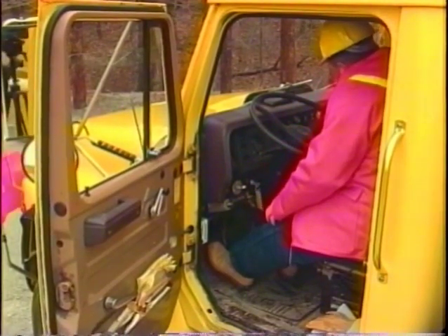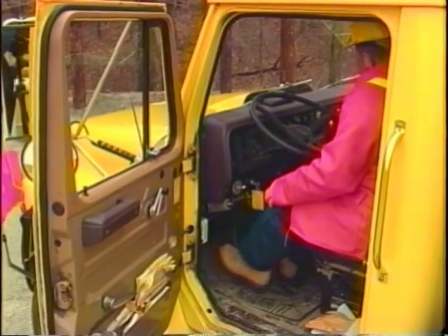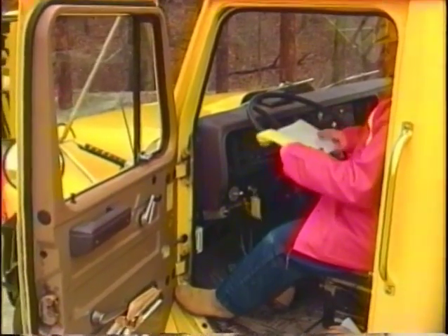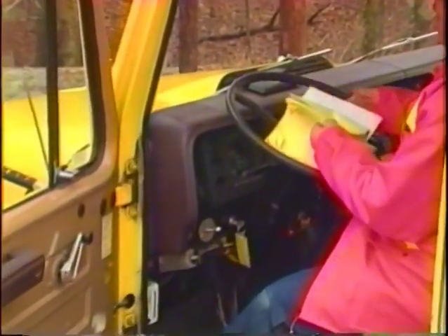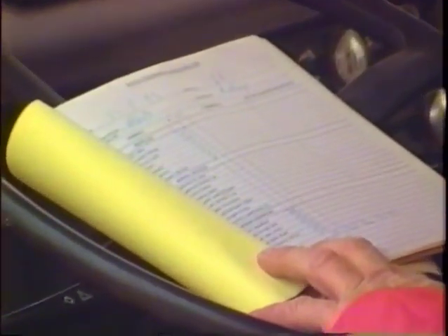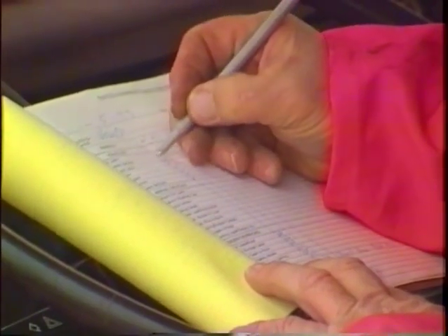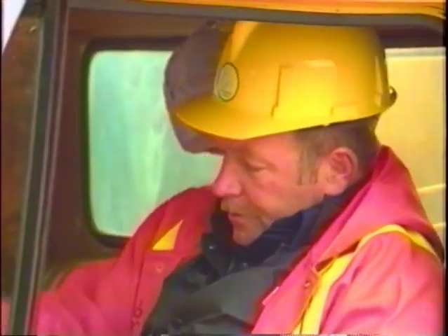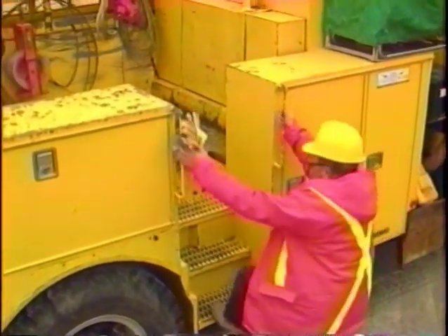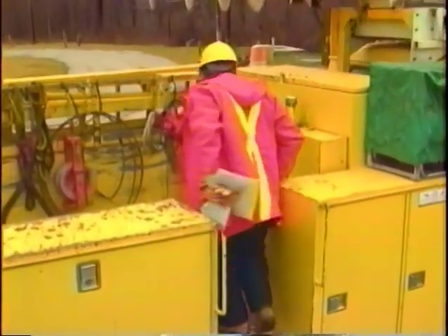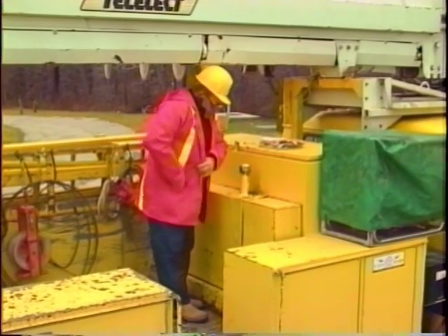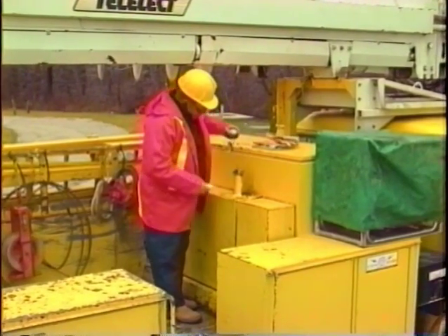It may seem surprising, but in the first part of your hydraulic check, you don't look at the vehicle. Instead, examine the vehicle's logbooks. Are the filters, strainers, or magnetic plug due for servicing? Does the oil need to be changed? If so, arrange to have the work done by a qualified mechanic. The next stage of your hydraulic inspection takes place at the reservoir. Start by checking the level of fluid in the reservoir using either the dipstick or the sight glass.